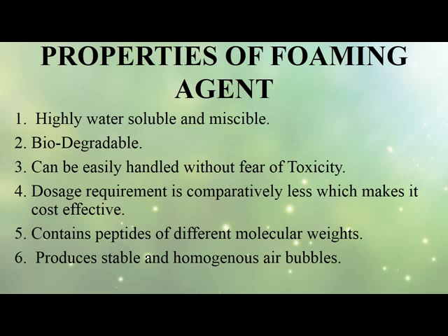The properties of the foaming agent we used are: highly water soluble and miscible, biodegradable, can be easily handled without fear of toxicity, dosage requirement is comparatively less, which makes it cost effective, contains peptides of different molecular weights, and produces stable and homogeneous air bubbles.